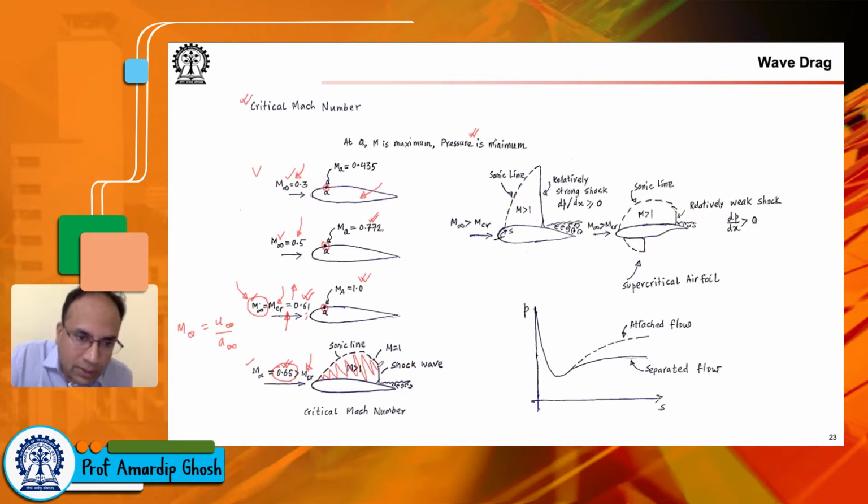The shock wave, as we discussed briefly, of course, this is something that you will learn in courses on high-speed aerodynamics, the nature of the shock wave, what happens across the shock wave, etc. But we said that the pressure jumps, the static pressure becomes very high, depending on the strength of this wave. So you have a terminating shock wave. The sonic line essentially tells you that at these locations M is equal to 1, which means if you calculate the U at these locations, divided by the velocity of sound at those locations, you will get M equal to 1.